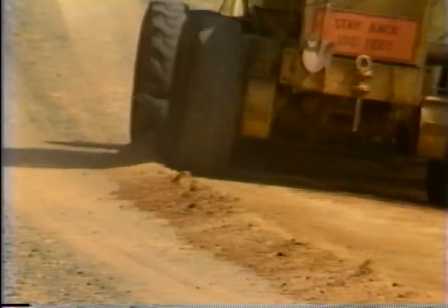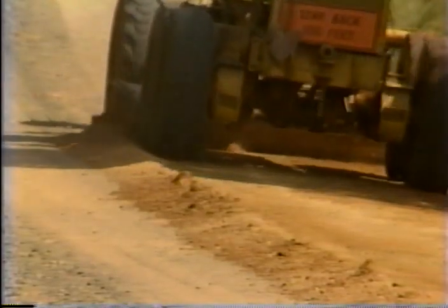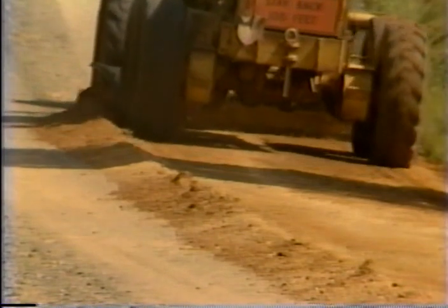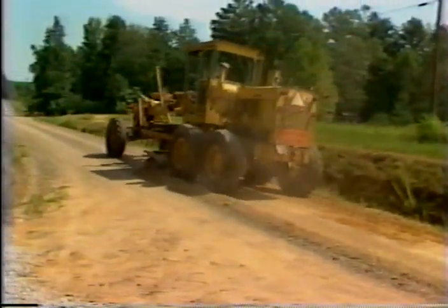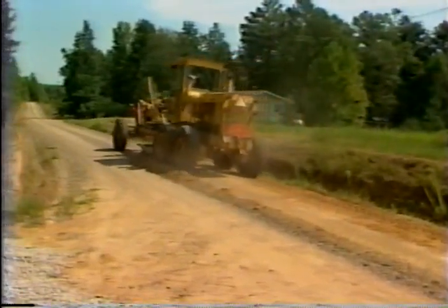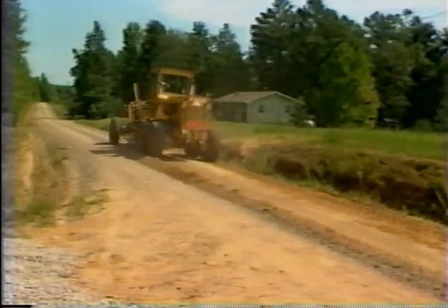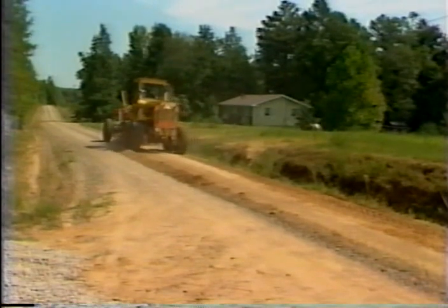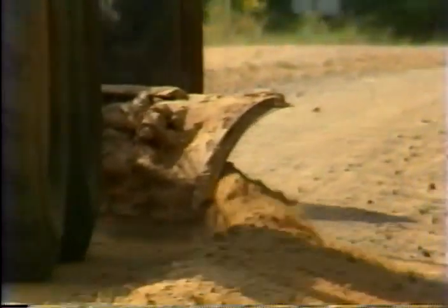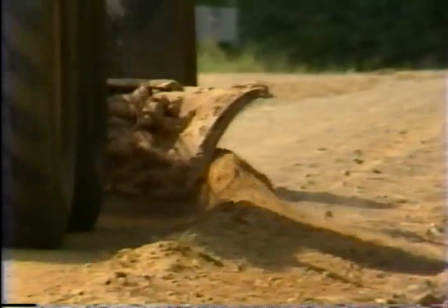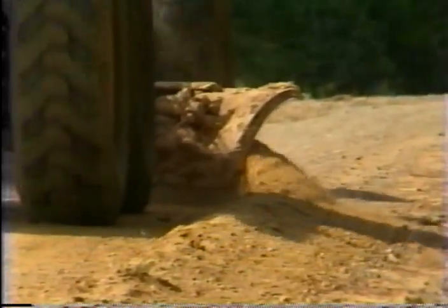Pull materials from the shoulder of the road across the blade, forming a windrow near the center of the road. Be careful that material does not spill off the toe of the blade and create a windrow at the shoulder of the road. This creates a small berm or secondary ditch and prevents the drainage of water off the surface of the road.